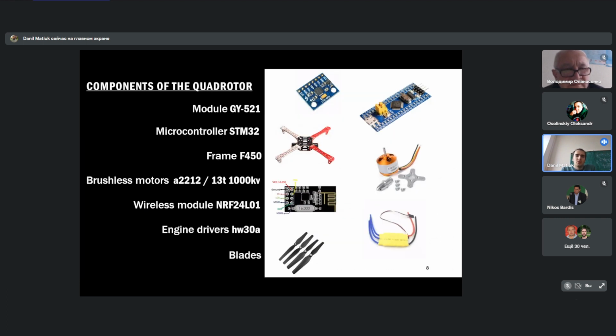To calculate the deviation compensation and bring the quadrotor to the required position when solving the problem of flight stabilization, a PID controller is used. When stabilizing, all three axes must be taken into account, namely the roll, pitch, and yaw angles. Direct control is carried out by calculating the amount of effort with which the quadrotor tries to compensate for the angles of deviation at each iteration of the control period. The proposed stabilization system was tested and validated on a real assembled quadrotor.